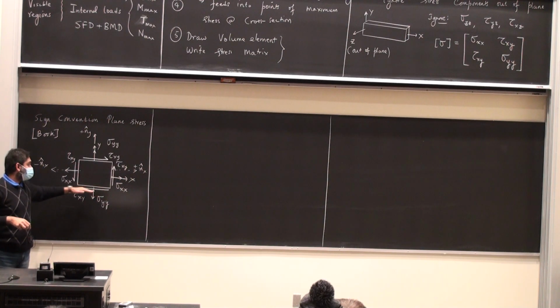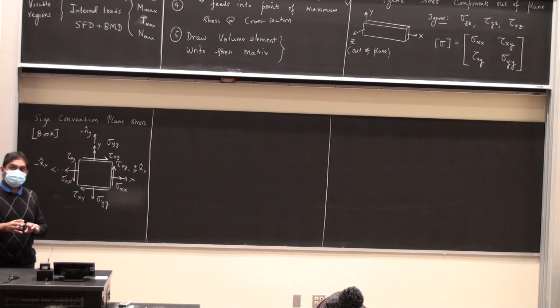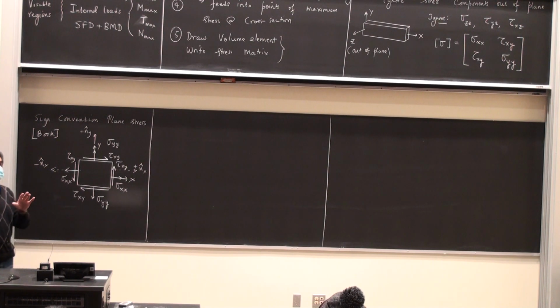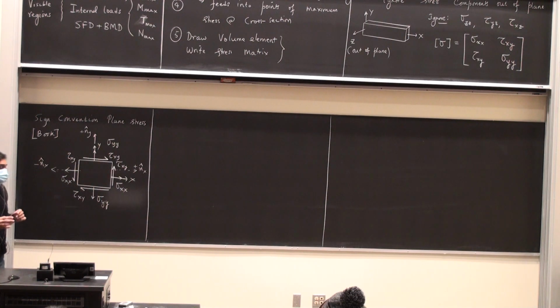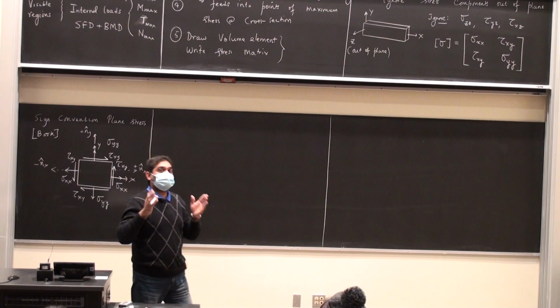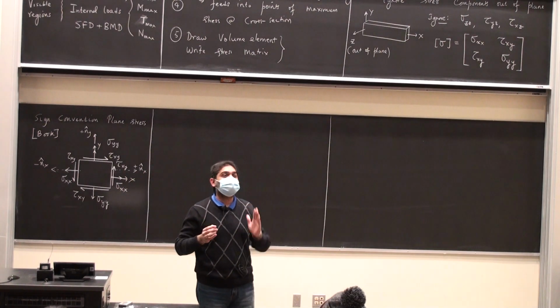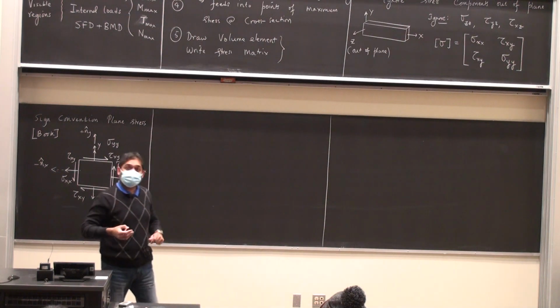And on the other side it's going to be pointing the other way. Okay? This can become confusing, because what we earlier on said was that if I'm drawing internal shear forces, they have to put this piece in a clockwise spin. So what is the truth here? The truth is that the problem will tell you what is the shear stress value and what is the proper sign of the shear stress. What is the proper direction? That is coming from solving the combined loading problem.